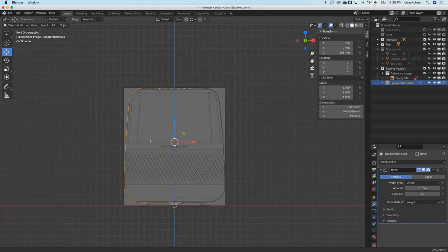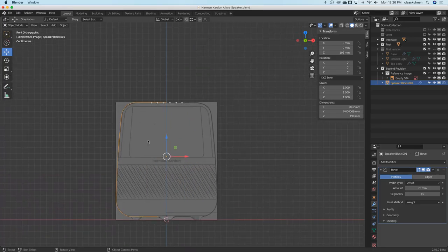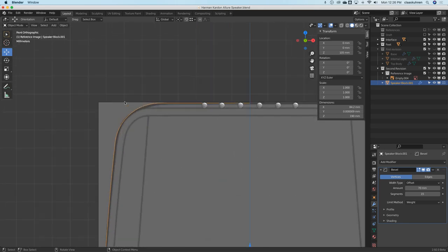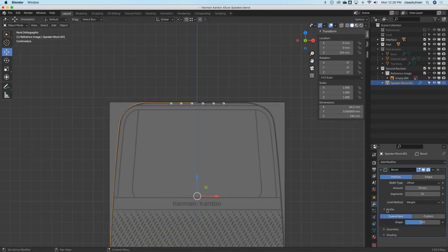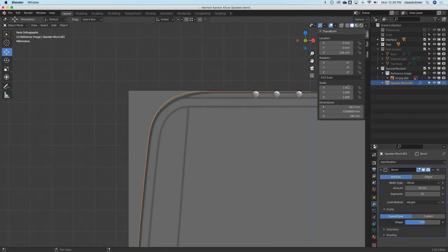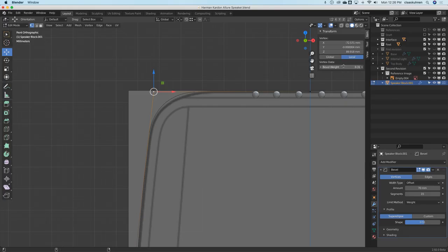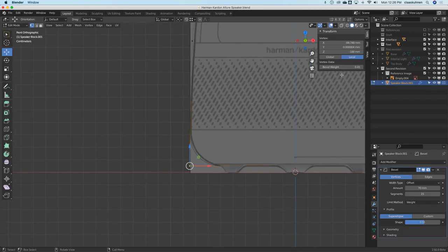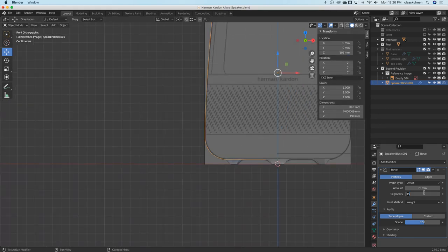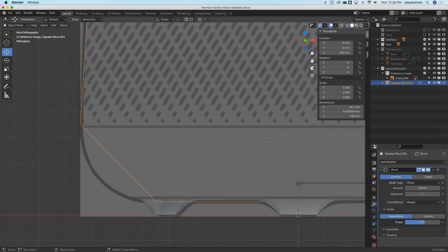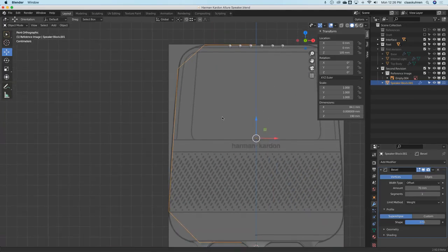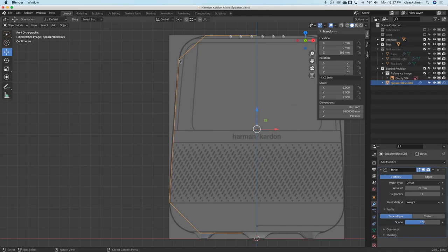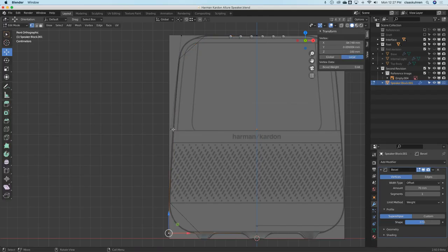And that's actually as you see so far, it's actually quite easy to do. Maybe we can go to profile 0.55, make this a little bit softer. Then we can change this a little bit, increase this a little bit. Okay, and I'm switching this back to 1, because what I would like to see is where are actually the start points of these fillets.